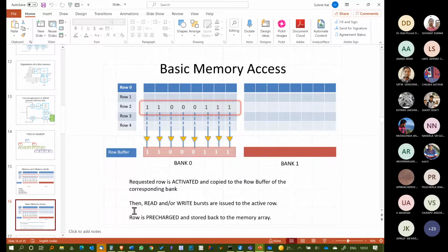Fine. All right. So this sense amplifier is read into the CPU, and then it is rewritten to another part of the memory. If you want to shift something from the memory to the memory, you have to involve some temporary register, and memories don't have a temporary register. So that temporary register has to be borrowed from something inside the CPU. So read from the memory, turn the cycle of memory access into write, and write into memory.